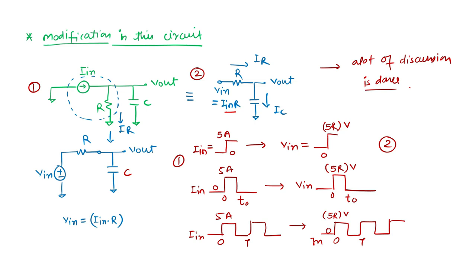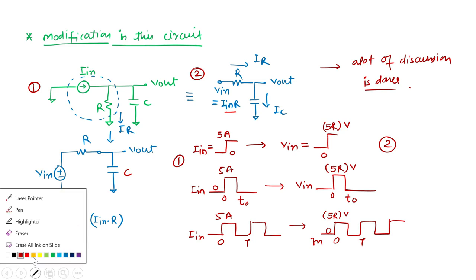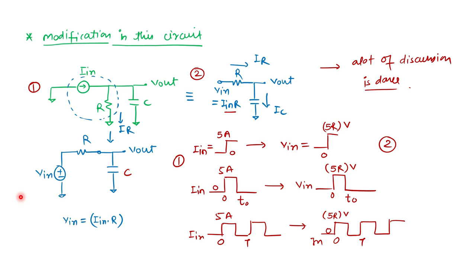circuit well, then before going into the calculations, you should analyze whether you can reduce your circuit to one R and one C element with the input as a voltage, because we have analyzed this circuit a lot. So there is a possibility of reducing the circuit in that fashion. There is no need to deal with the current source if you can convert it into a voltage source and a resistor only. So here the source transformation is working for me.